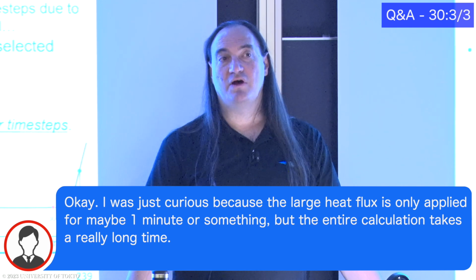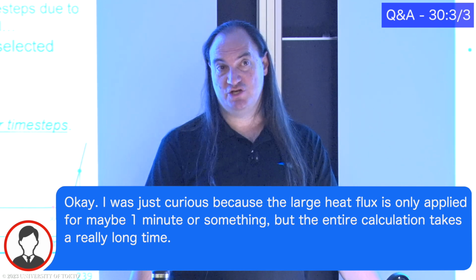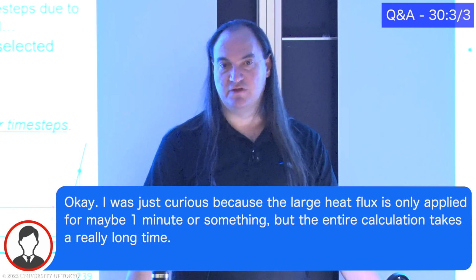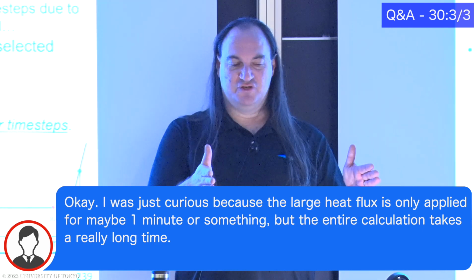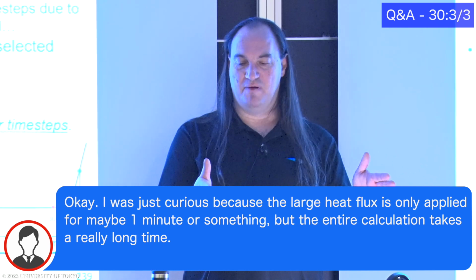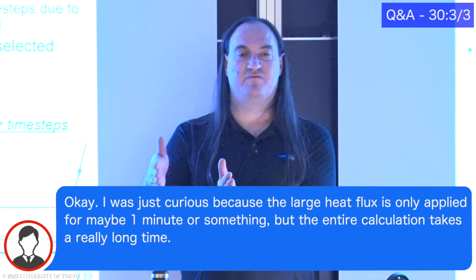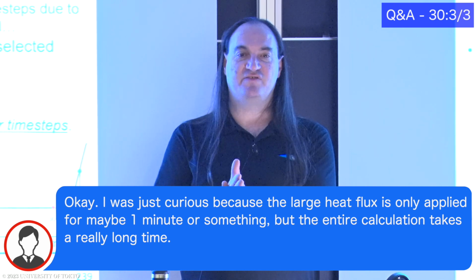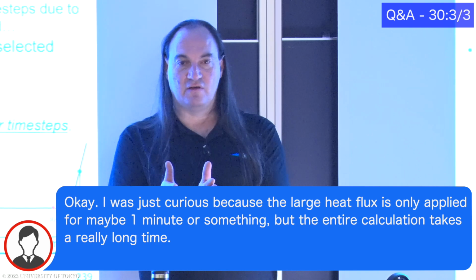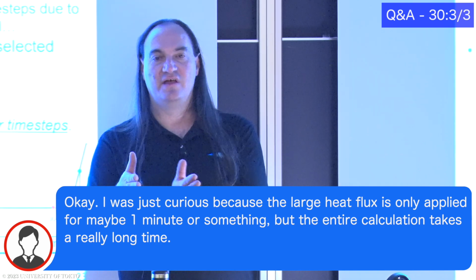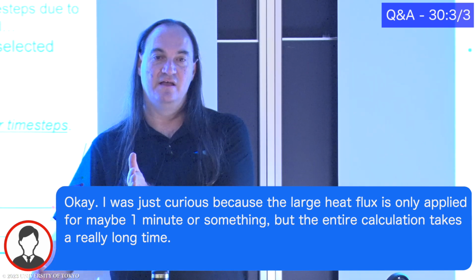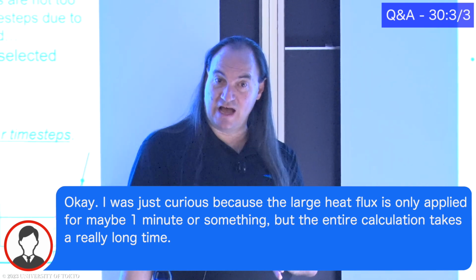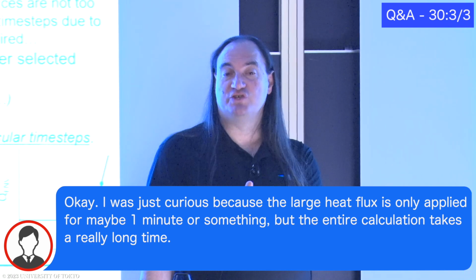So what you could also do is change the time step as you march through the solution. So you could say, all right, you know what? I want you to take 30-second time steps, but once you're within 30 seconds of this thing, I want you to change the D time I to be 1/10 of a second, and then start going very, very slowly. Okay, now we're past this. Now reset back to that. Oh, so the D time I is a variable that you can adjust as the solution is proceeding.